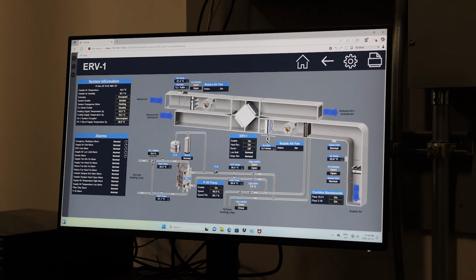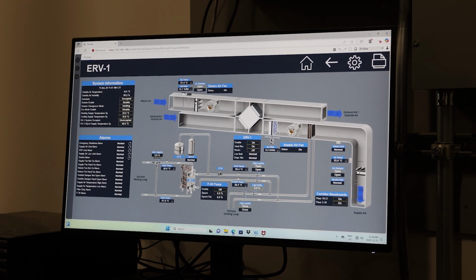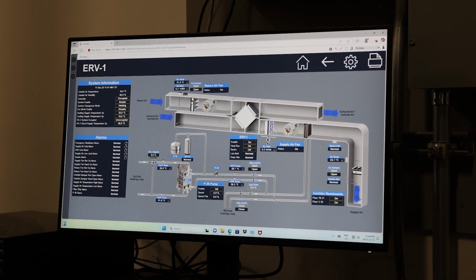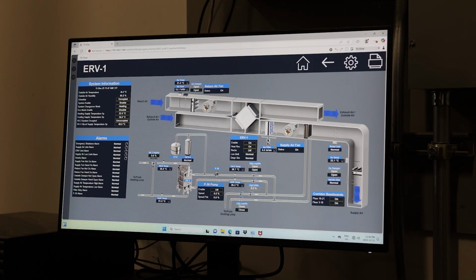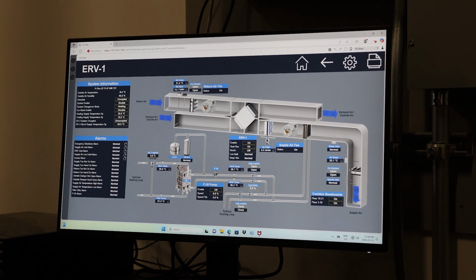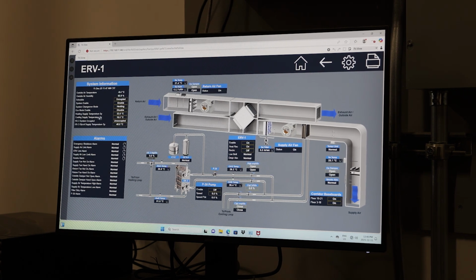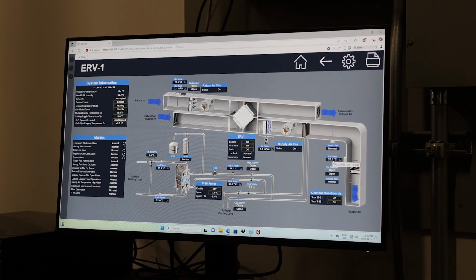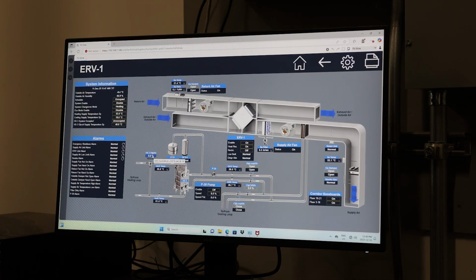See, right now, this isolation valve, they are closed, so there's no flow going this way. And all the flow comes from this pump. Flow goes to here. Now it's the heating side. Then heat exchanger 3. This is a 3-way valve that modulates to maintain supply air temperature. So supply air temperature set point is 22. Now it's maintained pretty well at 23. So this temperature is above the set point. So that's why the valve is already fully closed. Once this temperature drops below 22, this valve will start opening again.